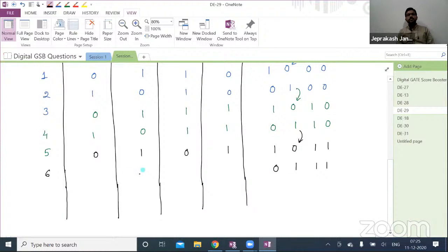Now with the help of this you can write Q3 is 0, Q2 is 1, Q1 is 1, Q0 bar is 0. Seventh clock pulse, you will get 1, 0. Here is a 1 to 0 transition. So what is the output here you will get? All of you please respond. For these two bits, what is the output? 0, 1. Yes, very good, Michael, because here you have 0, 1, so you'll get the output as 0, 1, right? Next, Q3 is 1, Q2 is 0, Q1 is 0, Q0 bar is 0. Next, the 8th clock pulse we are applying. Here you will get 0, 1. Since it is a positive edge, it will remain the same, right?